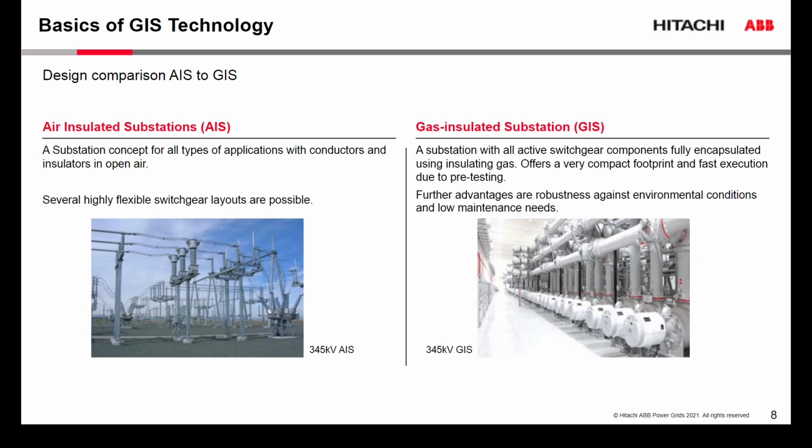The safety clearance on such equipment, we are talking about inches, even at the same voltage level. And with that reduction of size and safety clearance, we are creating the advantages of this technology, the GIS.